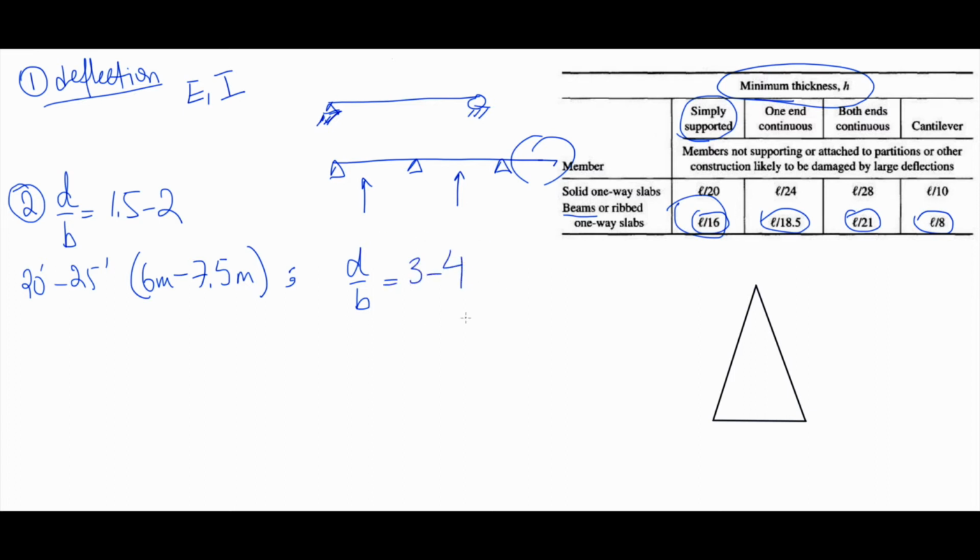But guys, you have to check with the architect. I mean checking with the architect because you don't want a very deep beam that is really visible to customers or the end users, so it will be a problem.